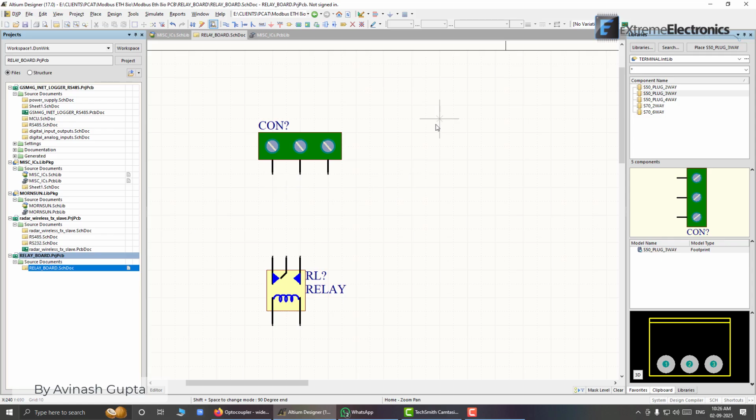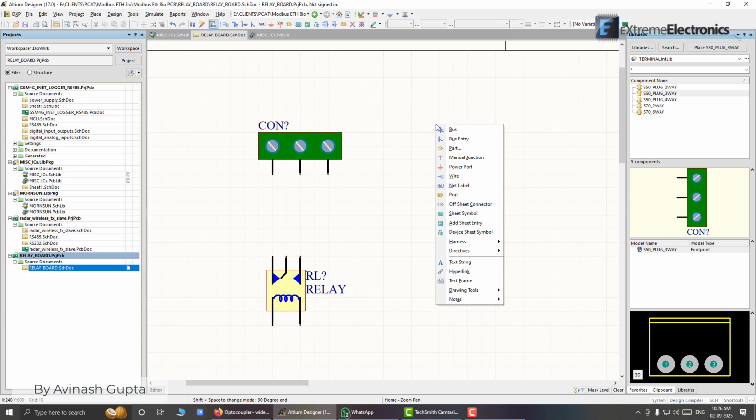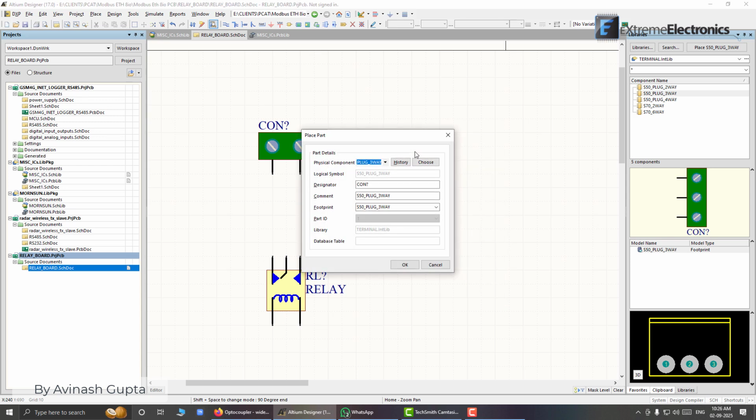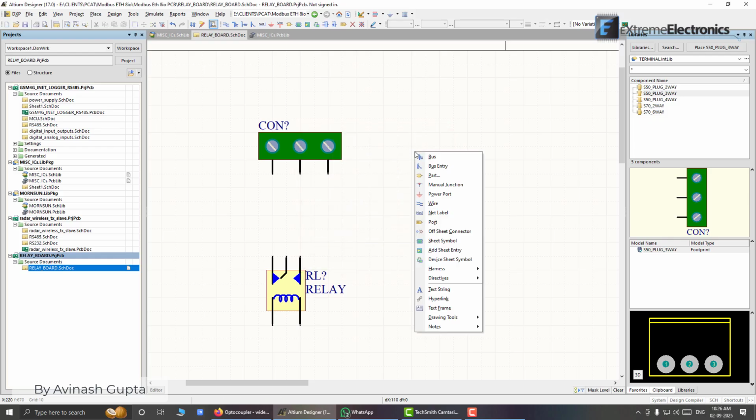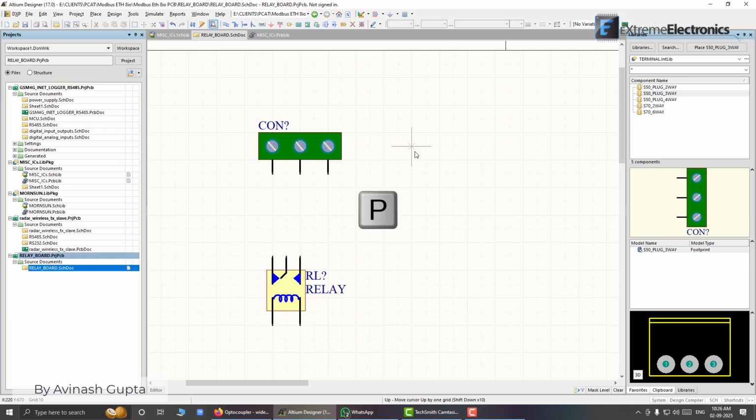Alternatively you can press this P, and instead of going to your mouse to select this wire, you can simply hit W on your keyboard. So this W stands for wire. So what you have to do is quickly press P and then W. It will activate the wiring command, and as soon as the wiring command is activated, your mouse pointer will turn to a crosshair like this.